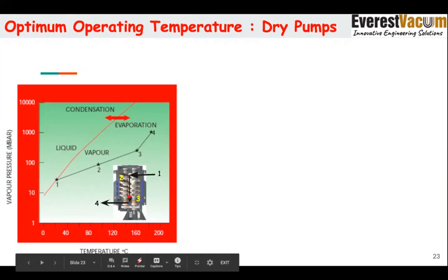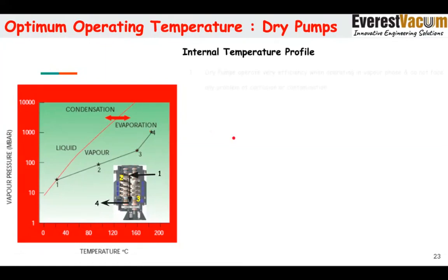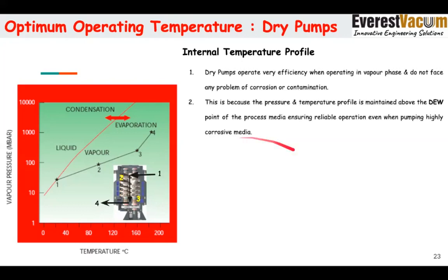Similarly here, because of the heavy compression at this point, there is a possibility that condensation might start occurring. To cope with that, what we have done is change the last two pitches so that we give a sudden jerk in compression to raise the temperature and ensure that there is no condensation happening within the pump. So I have tried to explain it in words also.